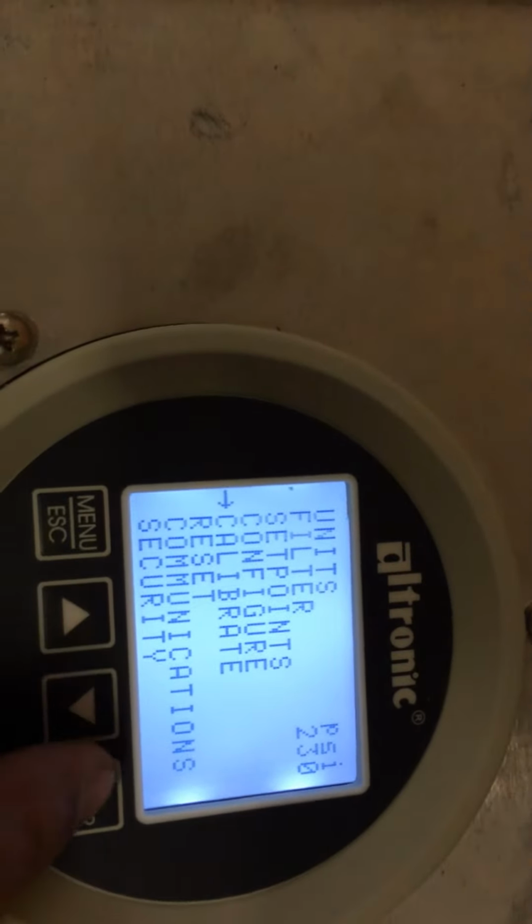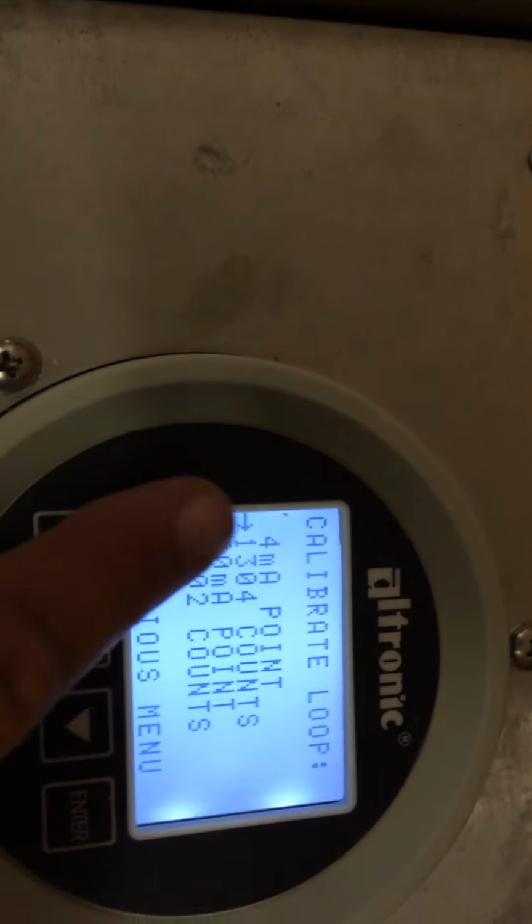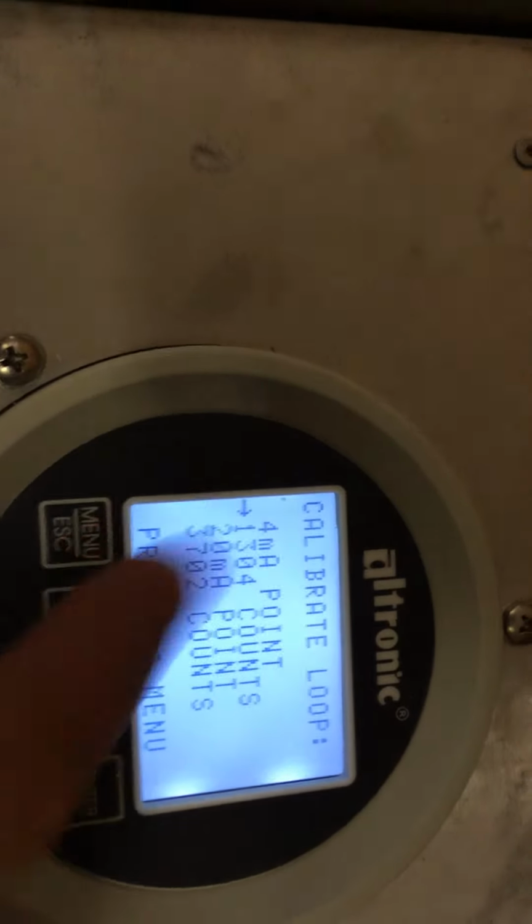And it keeps timing me out. I can go back into loop cal and line my cursor up there. It's going to be putting out that signal. I can use the switch on the panel that says manual and auto, go into auto, and watch that desired RPM.